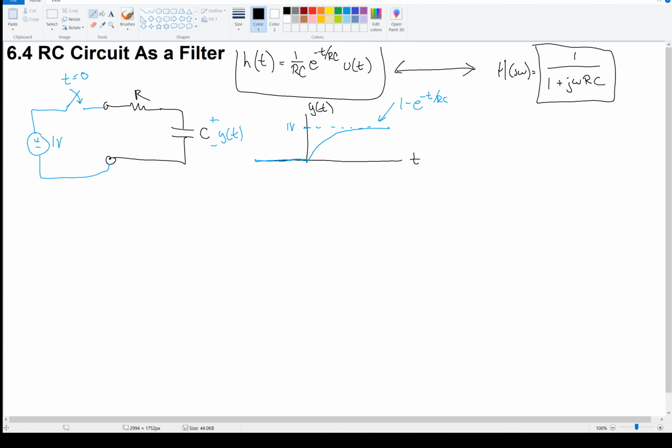So we're not going to use circuit analysis in our course, but we're going to see if we can get this using techniques that we've covered in our course, using the impulse response. Okay, so this here is the voltage across the combination, and we said that it's 0 until t equals 0, and then the 1 volt gets switched in, so the voltage looks like this. Well, what's that equation? Well, that's a unit step.